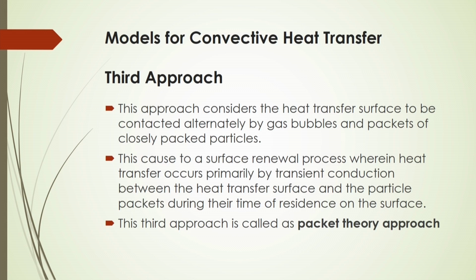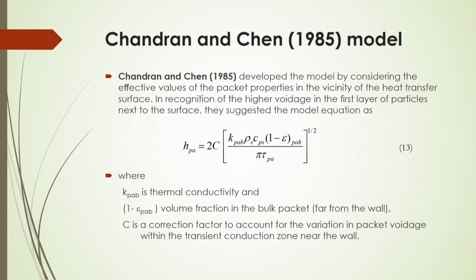That surface may be renewed by these packets of packed particles, and that is why a surface renewal process is considered in this case for the transfer of heat. So, this third approach is called the packet theory approach, which is basically based on the surface renewal theory.